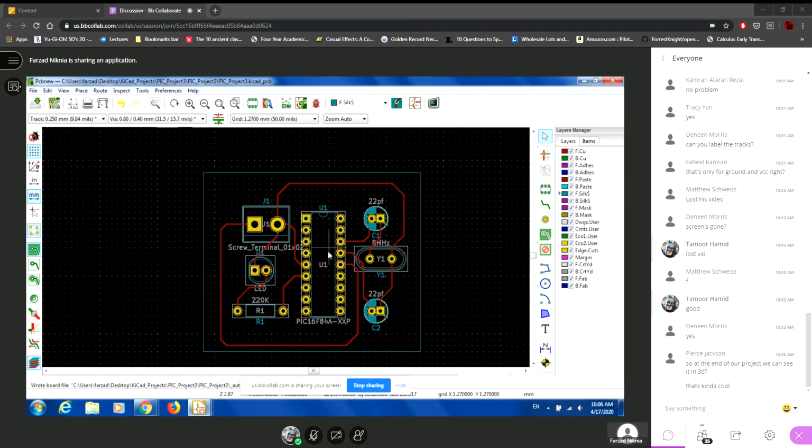For example, if your design is much more complicated and you can't find a way to connect all grounds and VCCs together, a practical way is to determine one more layer for VCC and one more layer for ground. In this case, you will be able to use some vias in order to connect your track to VCC or ground in every place on your board.